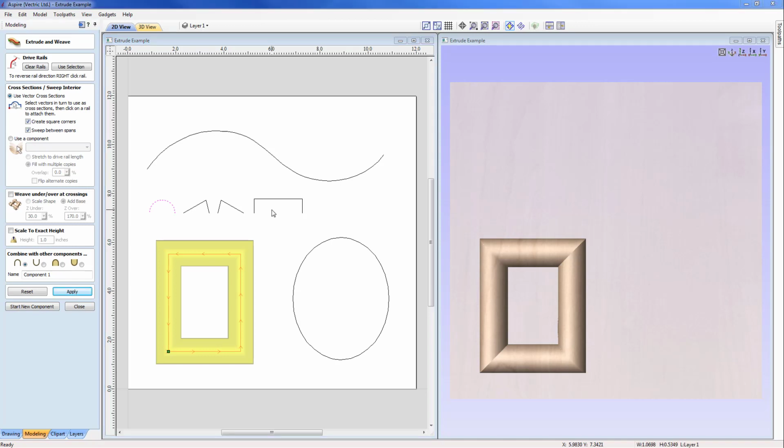Okay, so just like the open rail example, we may wish to take another cross section and add this into the component. So at the moment we are just using the semicircular shape all the way around, but let's say for instance I wanted to take the upper right hand corner and add in the triangular shape into this region. But what I want to do is make sure I add in the control in the fact that I want rounded in the top left hand corner and rounded in the bottom right hand corner, and only have the transition through the upper sort of right hand portion of the component.